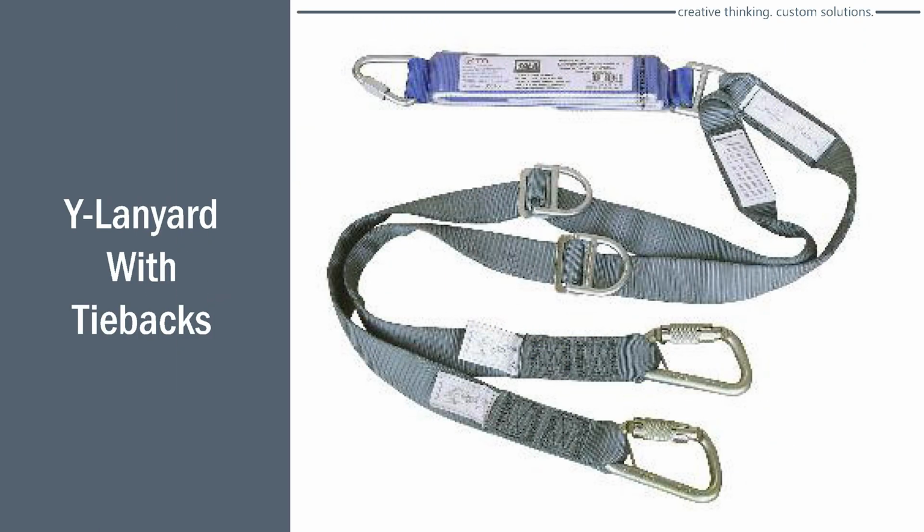All right. This is what I mentioned earlier. We were talking about lanyards that have tiebacks built into them. Okay, so you got your D-ring and you got your auto locking snap hook. Of course, these cost you more money, but if you think about it, it's also going to lessen your fall distance. Right?